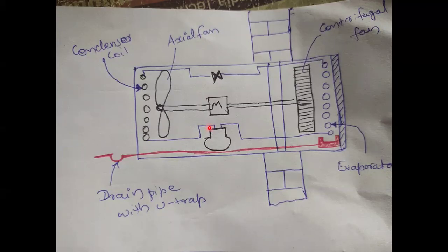Okay, so in the working of the VCR cycle, from the compressor you get a superheated vapor refrigerant at high temperature and high pressure, and it is passed over to the condenser side. On the condenser side, the atmospheric air should be in contact with the condenser coil itself. That's why the condenser and compressor arrangement should be placed outside of the room, isn't it? Or in other words, it should always protrude outwards. And you've seen in your homes, it has to be